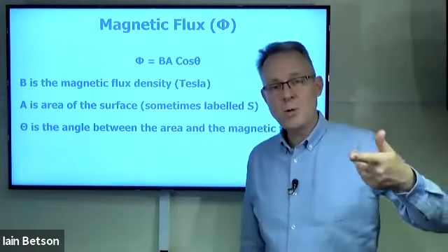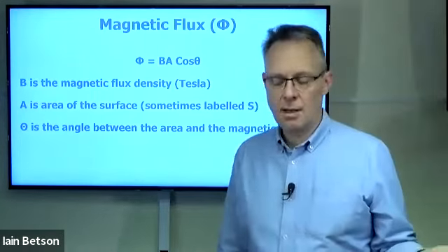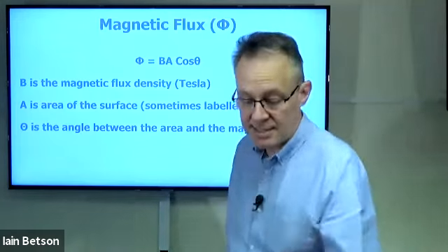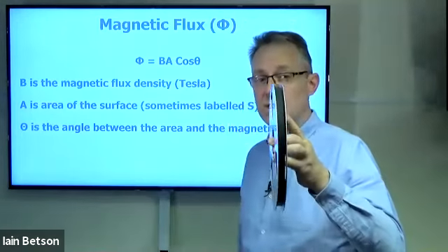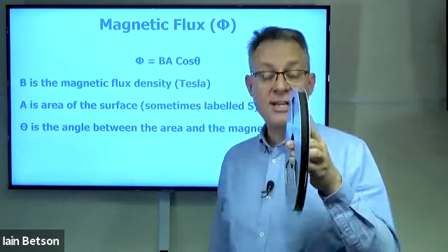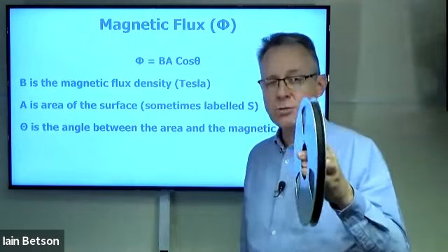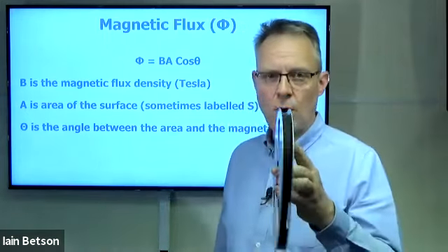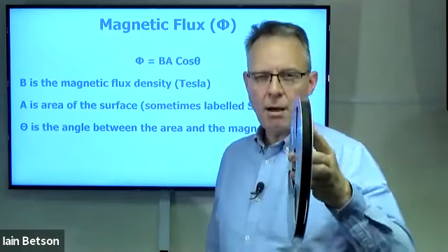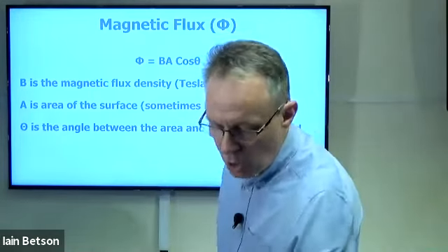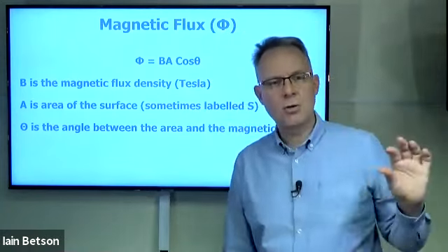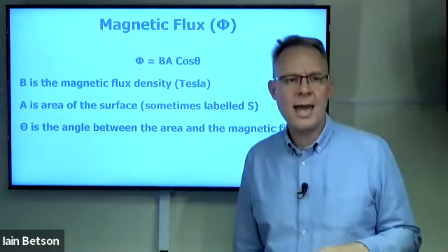Similarly, you could go the opposite way, where you get the high standard of recording and reproduction. That's using something like a 1/2 inch tape with a stereo head. So there's only 2 tracks recorded on this 1/2 inch tape. Extremely wide tracks on the tape, wide guard band so we don't get crosstalk, and a big wide track imparting a lot of remanence, a lot of flux back into our heads.